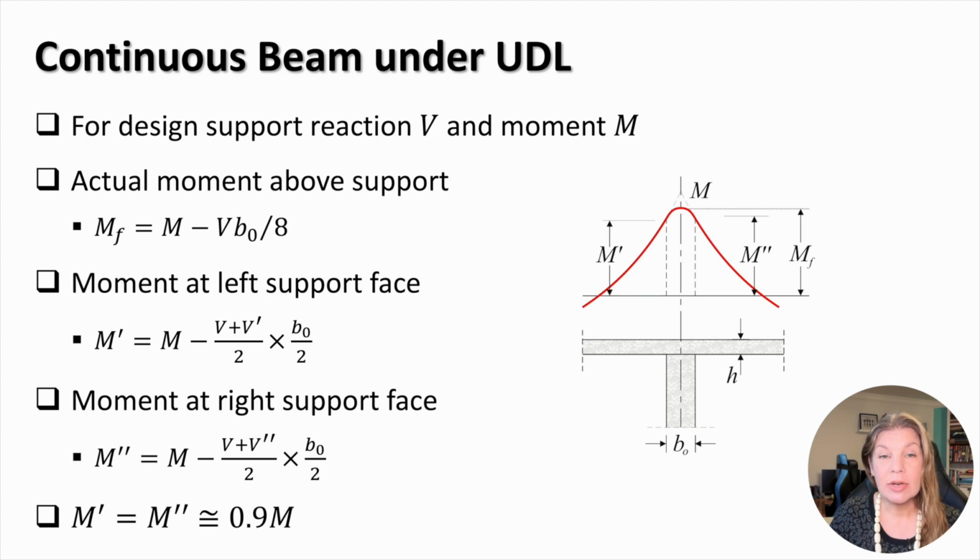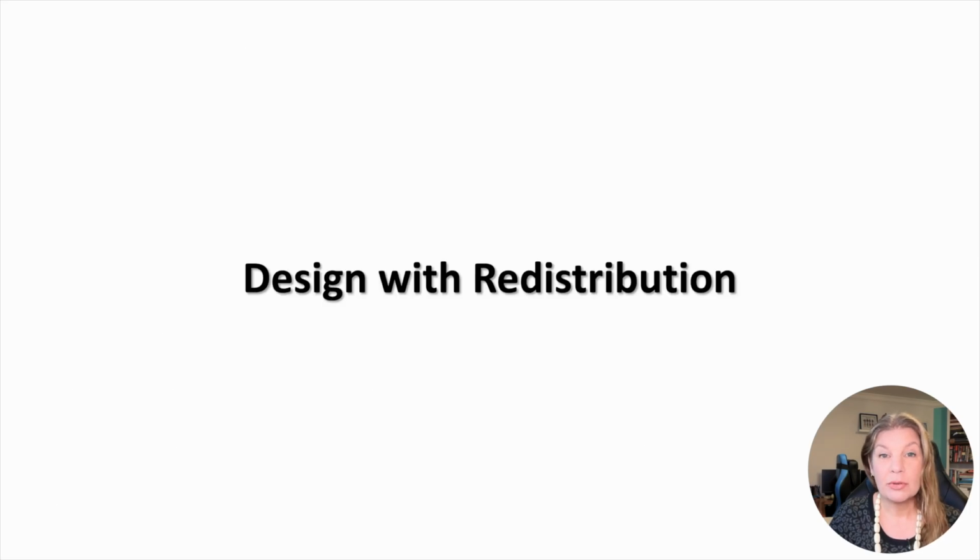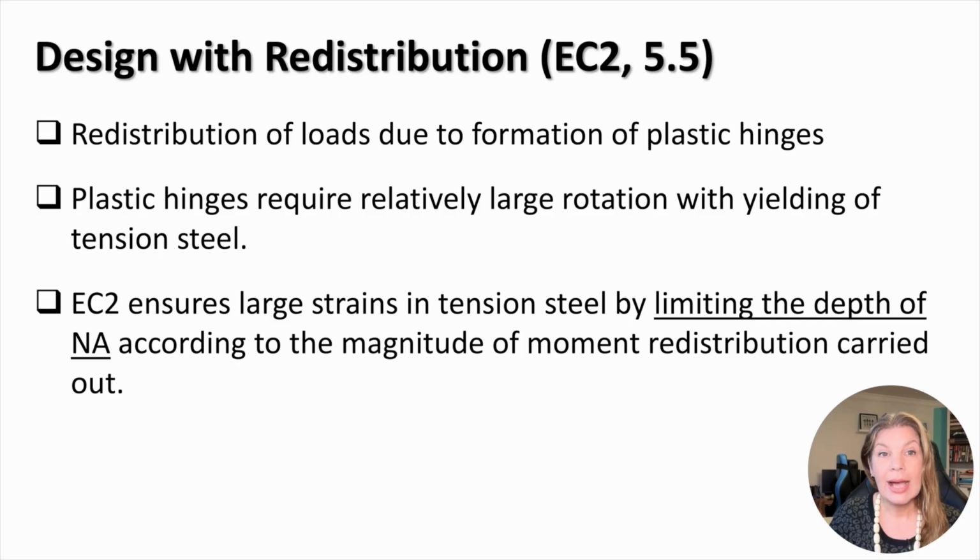Note that these considerations are usually disregarded in the design, making it more conservative. After understanding what moment redistribution is, we can discuss the process of design with redistribution established by Eurocode 2. As we discussed, redistribution of loads occurs due to the formation of plastic hinges.